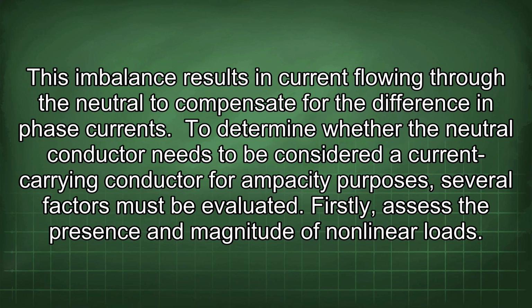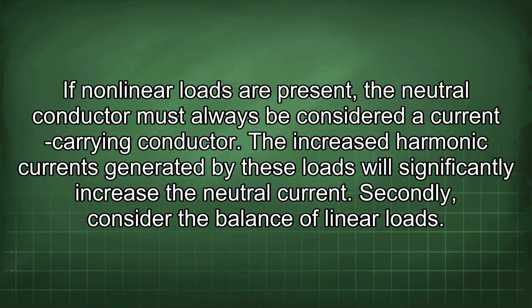To determine whether the neutral conductor needs to be considered a current-carrying conductor for ampacity purposes, several factors must be evaluated. Firstly, assess the presence and magnitude of nonlinear loads. If nonlinear loads are present, the neutral conductor must always be considered a current-carrying conductor. The increased harmonic currents generated by these loads will significantly increase the neutral current.